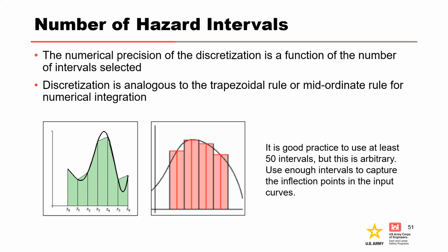We develop a branch for each hazard partition, assign the system response probability and life loss that best represents the interval, and then the frequency or the y value of the trapezoid will be the product of the hazard probability times the system response, and the x value will be the change in the consequences. We can then multiply x and y for each trapezoid to get each area and then sum them up to get a good approximation of the area under the curve.